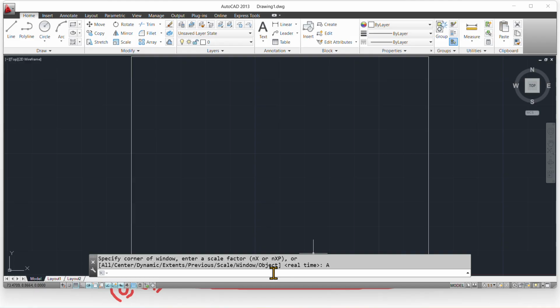First we will draw point 1. For that I will be using a command called line, and it is asking for the first point. I will be giving my first point as 20 comma 20. You can see here I will not be using any at-the-rate symbol. I will always consider my first point as an absolute coordinate. From then on I will be using the relative coordinate method. The first point is 20 comma 20.